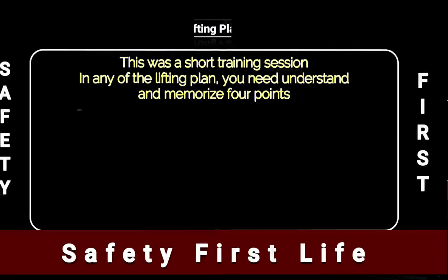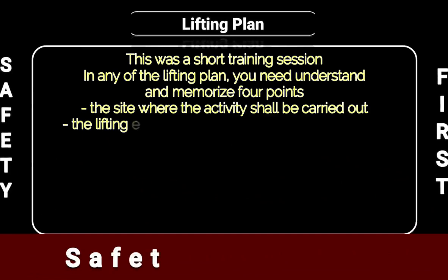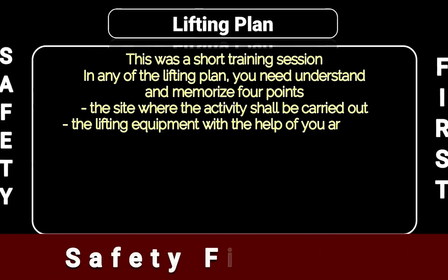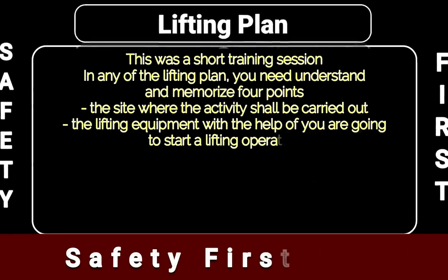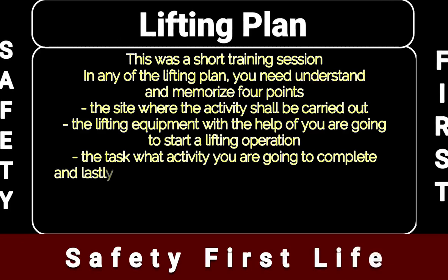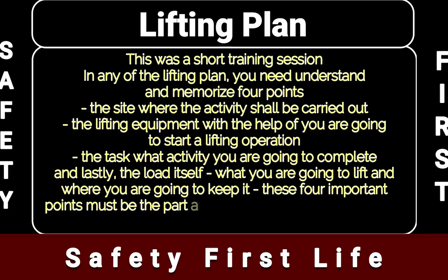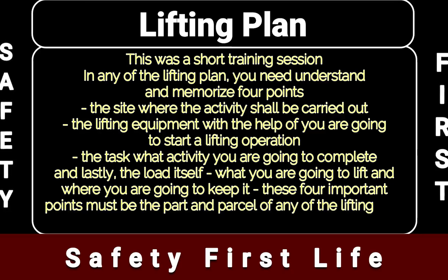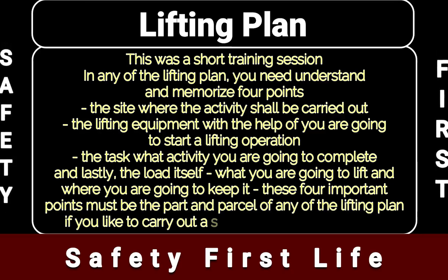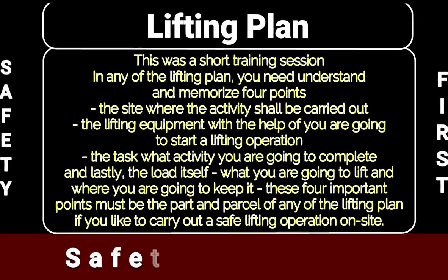This is a short training session. In any lifting plan, you need to understand and memorize 4 points: the site where the activity will be carried out, the lifting equipment with the help of which you are going to start a lifting operation, the task, what activity you are going to complete, and lastly, the load itself, what you are going to lift and where you are going to keep it. These 4 important points must be part and parcel of any lifting plan if you would like to carry out a safe lifting operation on site.